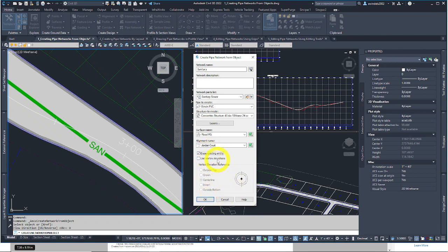Lastly, we could go to making which elevation to go to. This isn't that important right now, but just note, I'll keep it on center line. This is the different areas of a pipe. This is just good pipe nomenclature. Outside top, this is the crown of the pipe, the inner top, the center line is the very middle, the invert. This is one of our most key elevations of pipe design.